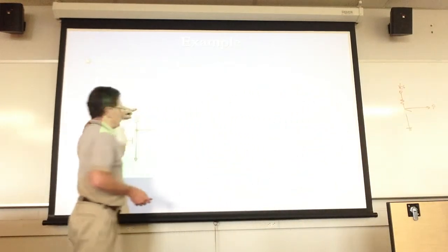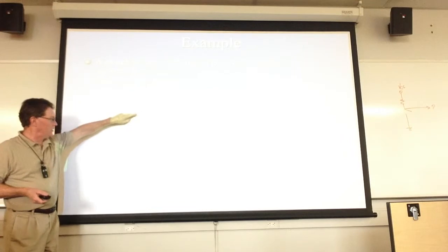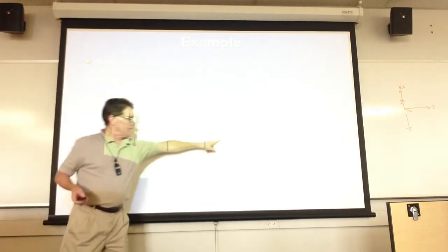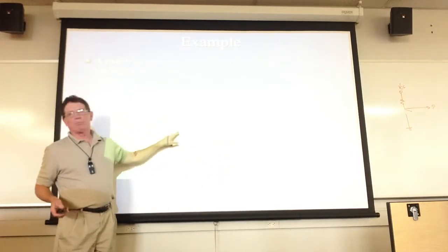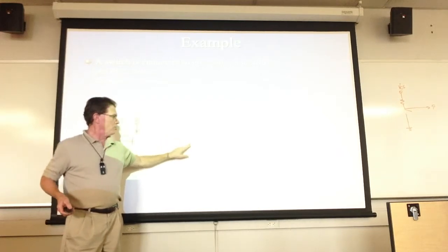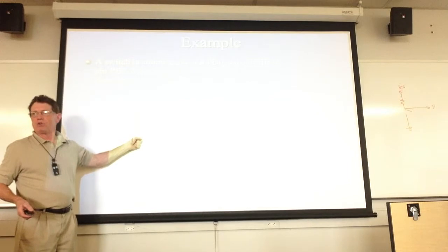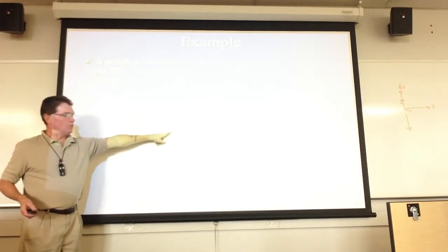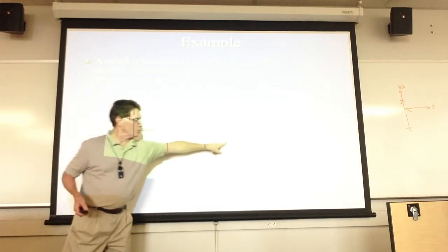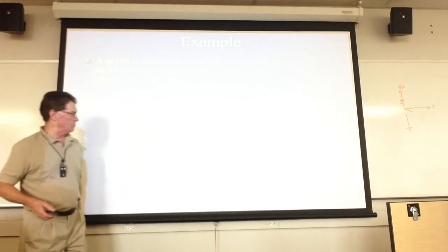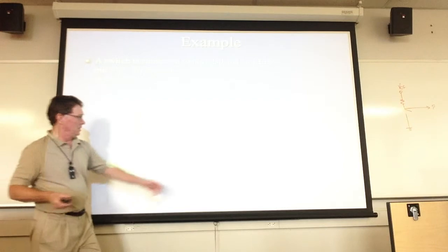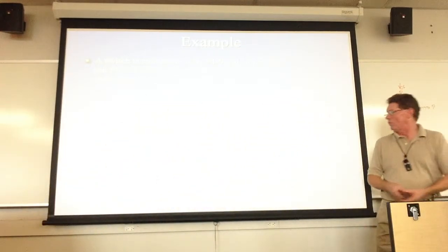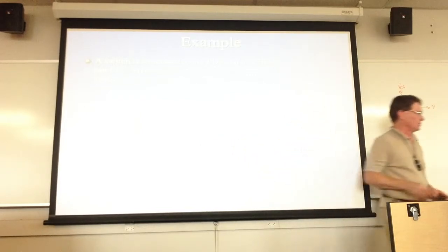All right, so I had a 4.7K resistor. VCC I tapped off of either port B or port D, and then I just had a switch here. I then had, I think it was a 270 ohm resistor and an LED here. So I'm going to read into port D, pin 0, and then I'm going to write out. When this switch goes active low, I'll turn the LED on over here. So that was the idea. I have the 8-pin dip switch, but I'm only using 1 switch. And then I just borrowed one of the 8 LEDs that I had on port B. It happened to be PB2.